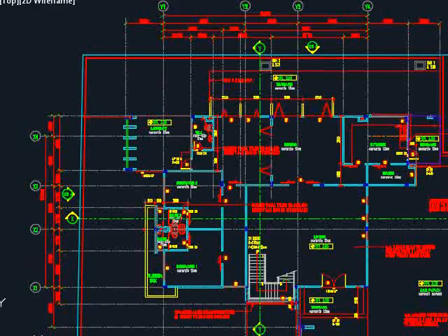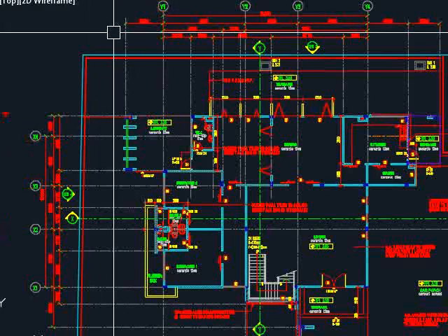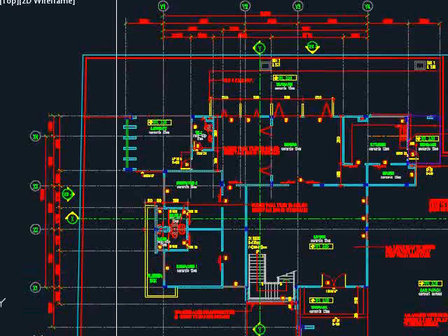Therefore, later when you need to produce your structural key plan, you're going to make all the horizontal grid lines x and all the vertical grid lines y, and you should adopt the same numbers in the same locations of the grid lines. That will be the bare minimum.